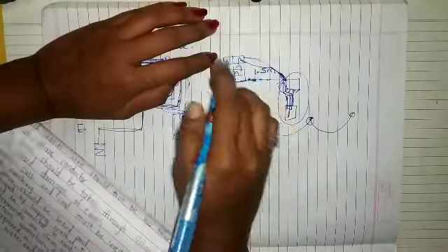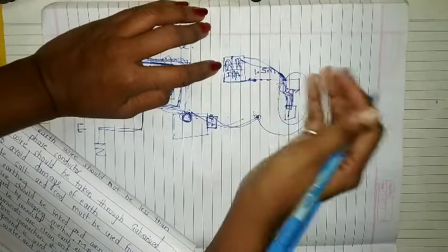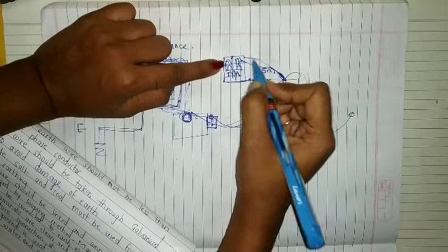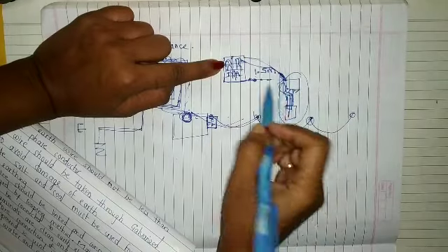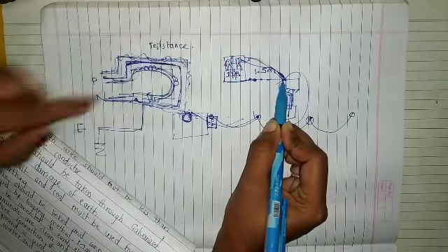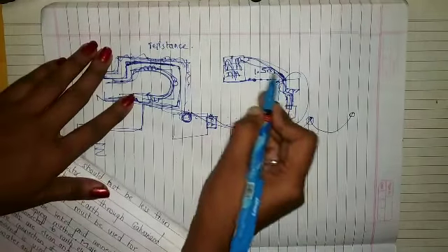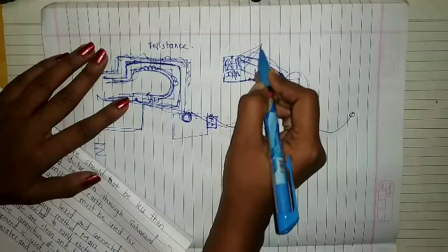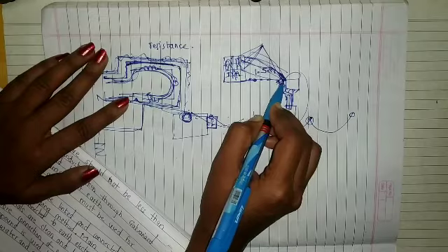Now consider this is a building, right? There are this many houses here. So every house will have one new earth wire, right? We have to connect all those earth wires into a single earth wire and then give it to this earth electrode. We must not give all the separate wires here. We have to join the separate wires and then give a single one to this earth electrode, right? So this is the point.